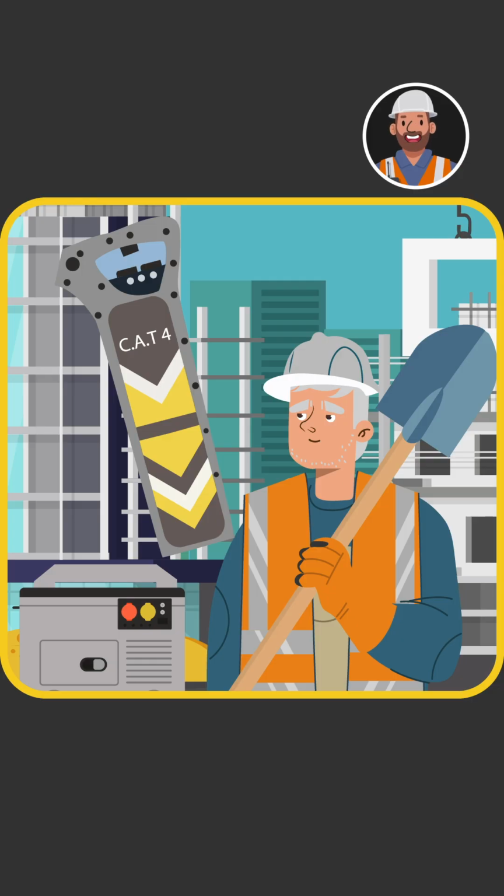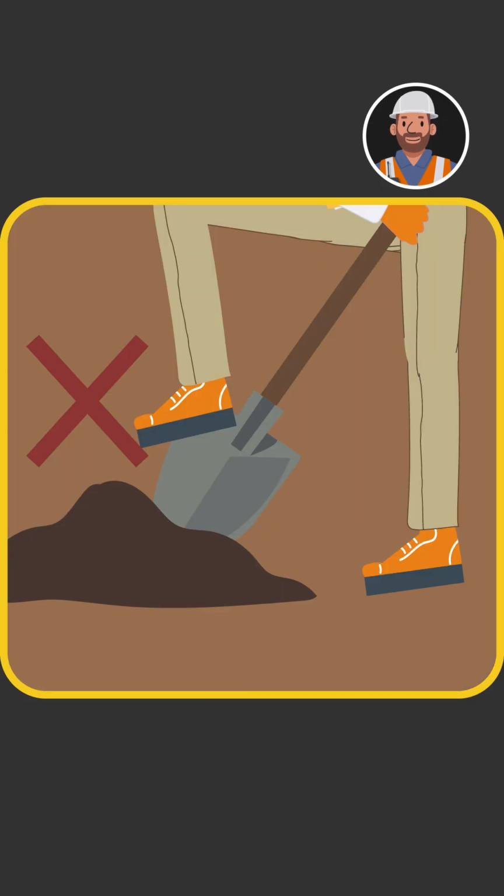Use insulated spades and tools to carefully expose buried services and confirm their exact positions. Never dig directly over a suspected service. For deeper excavations, continue scanning regularly as outlined in HSG 47.